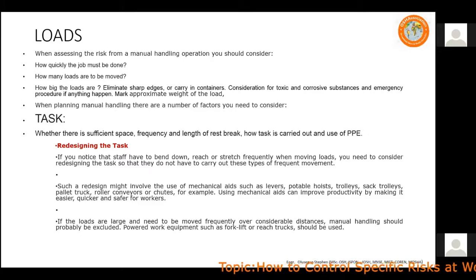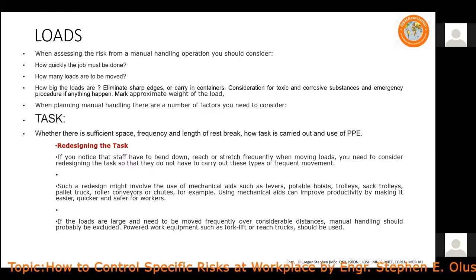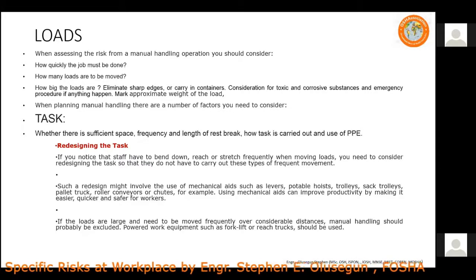If you notice that the staff have to bend down, reach or stretch frequently when moving the load, then you need to consider redesigning the work so that it can reduce the frequent movement. Such a redesign might involve the use of mechanical aids such as levers, portable hoists, trolleys, sack trucks, pallets, and conveyors.